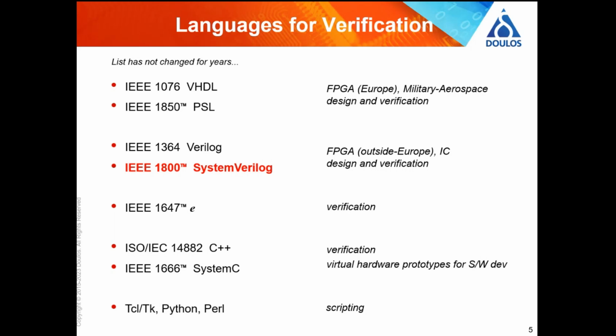Quite abstract, but not super abstract. Underneath that, we've got PSL, which is property specification language. It's actually part of the VHDL standard now, and that allows you to write the kind of rules that I was just talking about. If this happens, then that should happen.